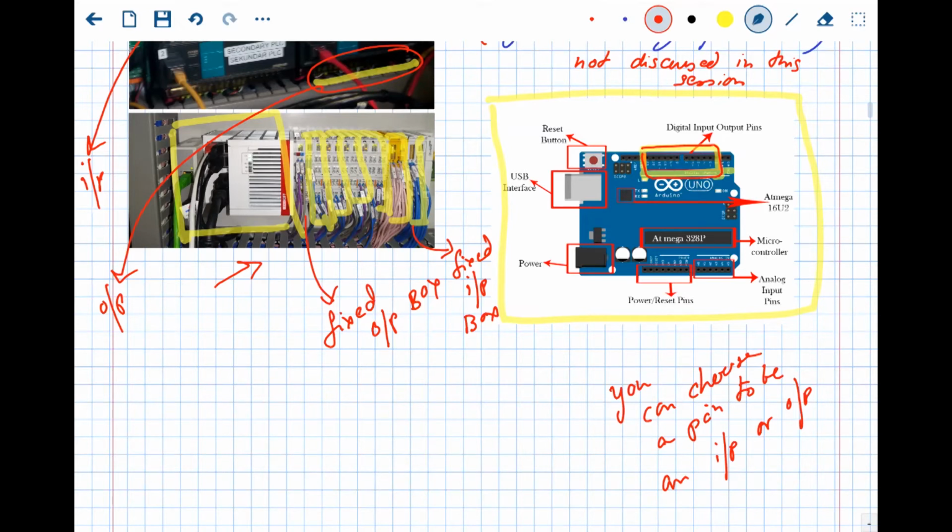For the PLC input output, because the inputs are made in a way where each box is set to operate in a particular fashion, they have internal circuitry to prevent the opposite. Because it's industrial, even if there is a polarity reverse, they have a lot of preventive circuits in the boxes, which makes things a little bit complicated, and they also have to cater to particular standards. That is why usually they do not allow this kind of system, because it can create confusion.